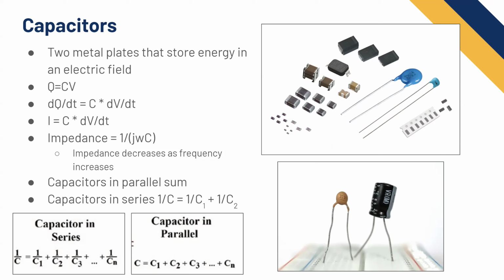It looks like the bottom plate of each capacitor is shorted and the top plate of each capacitor is shorted. So it looks like one capacitor, right? That's not the exact math, but it's a graphical way to think of why capacitors in parallel should sum. And then capacitors in series actually do the opposite, where the reciprocal sum is the reciprocal equivalent.